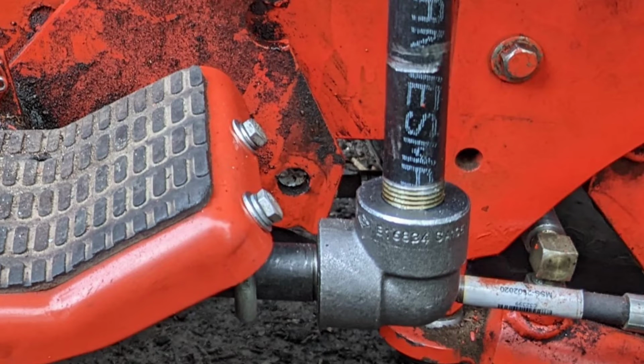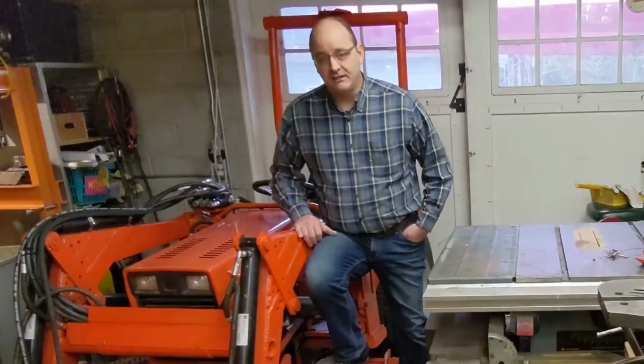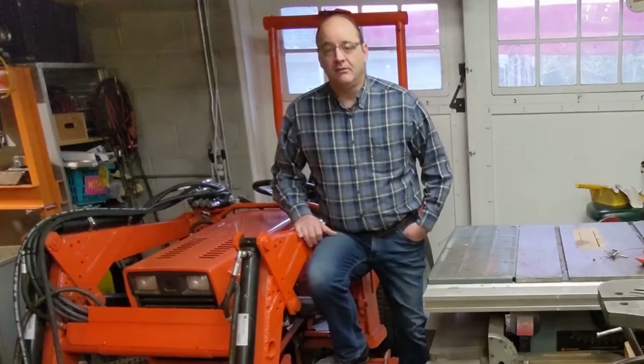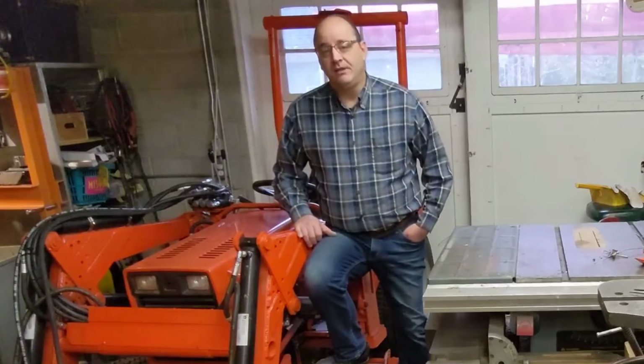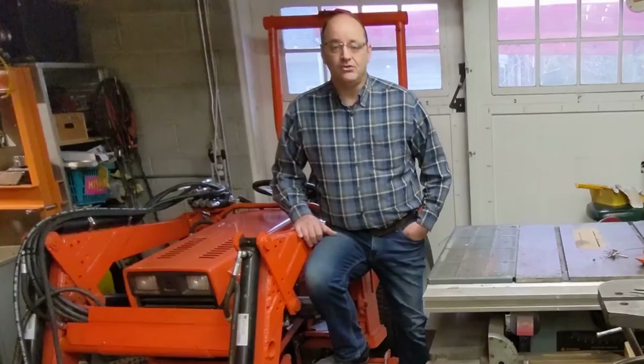I want to take a minute to note that I am not using standard iron pipe fittings for high pressure hydraulics. There is a dramatic difference between standard steel pipe and standard iron fittings. The pipe is rated at about 5000 psi, but the fittings are only rated for 300. Standard black iron NPT fittings cannot ever be used for pressure side hydraulics. They will absolutely fail, and probably explosively, causing damage to equipment or injury to people.